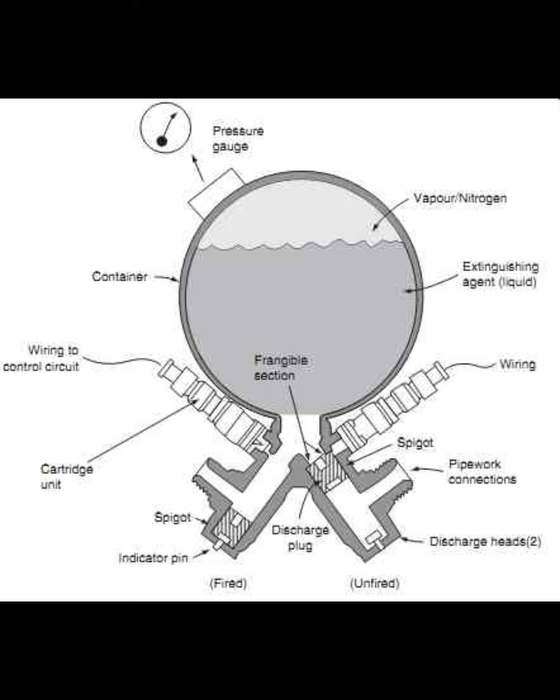What is the purpose of the yellow and red discharge plugs, discs, in a turbine engine fire extinguishing system? Yellow indicates pilot intended discharge, red indicates thermal activated. What are two methods commonly used to distribute the fire extinguishing agent to the engine? Perforated tube or discharge nozzles.